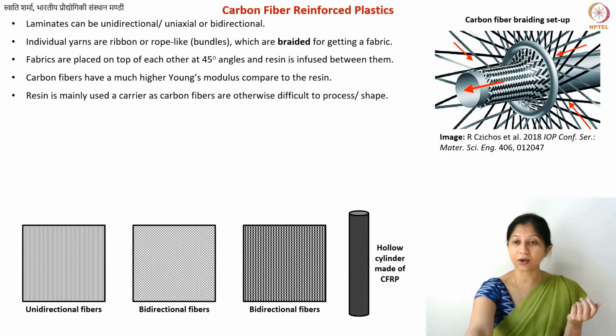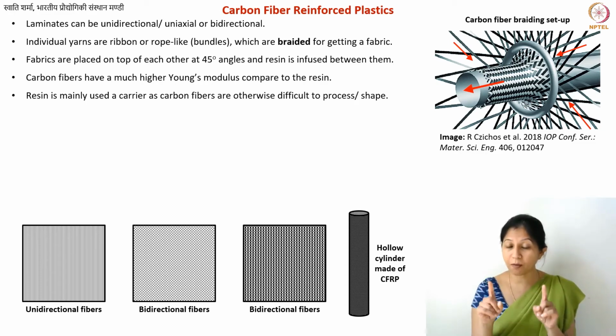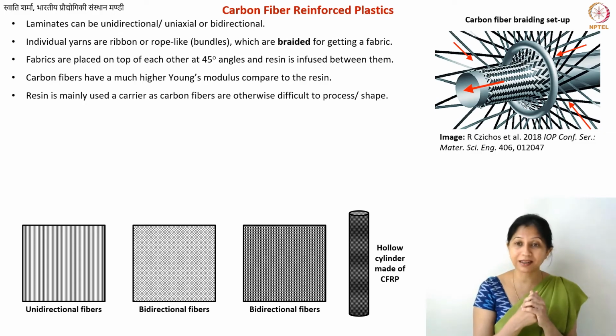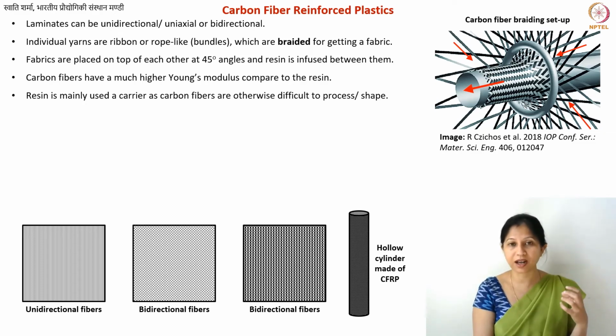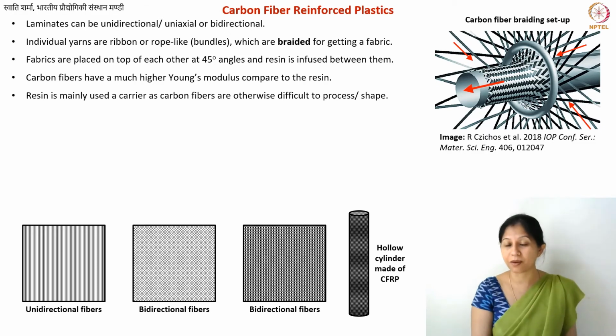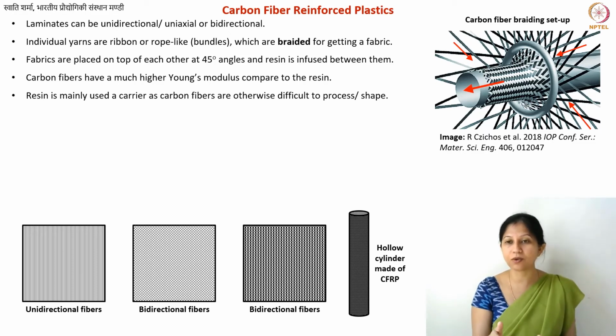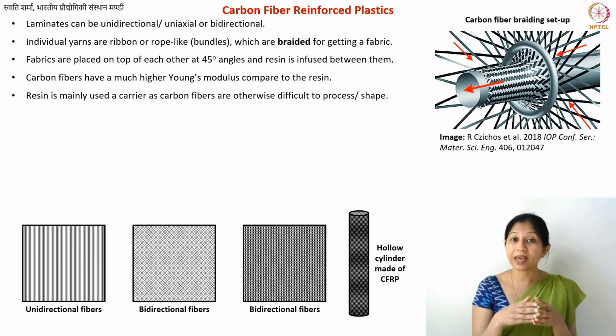Because typically you will have 50 to 60% carbon fibers in a carbon fiber based composite, so you also get it a little bit reduced. You also have about 60% of the Young's modulus that you had if you had measured just one yarn of carbon fiber. Compared to that, you will also have slightly reduced mechanical strength.